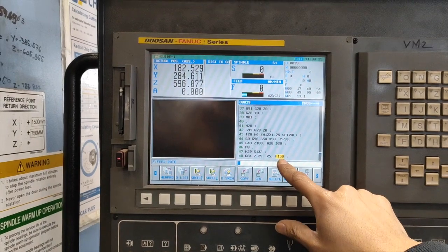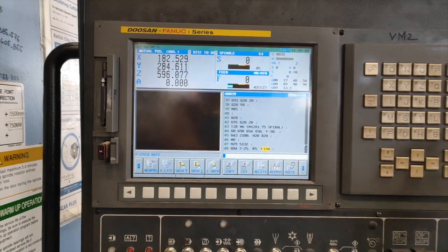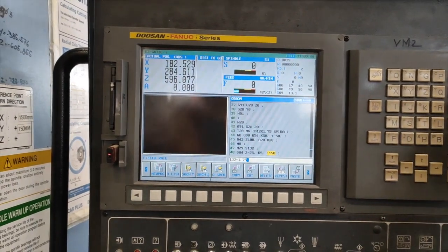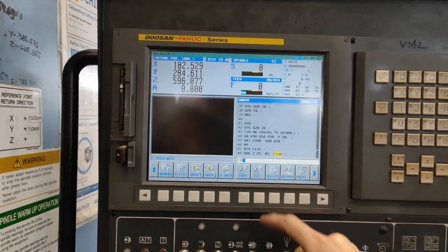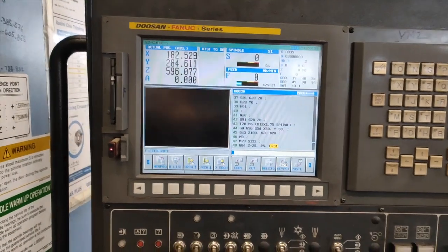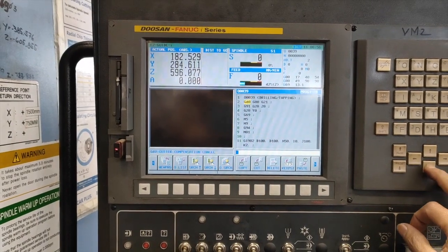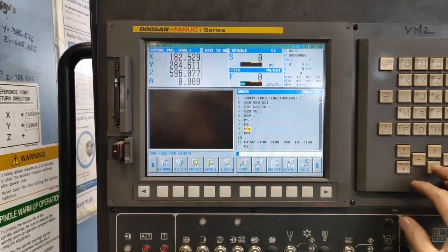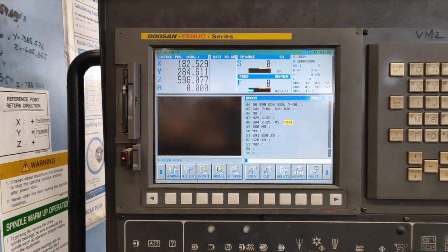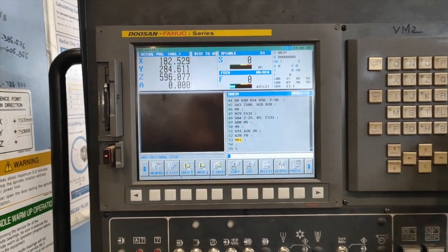And the feed speed, I'm going to multiply the spindle speed times the pitch. 132 times 1.75. So it's 231. Because guys, I'm using G94. I'm using G94. That's why I need to multiply the spindle speed with the pitch, and make this one M30.